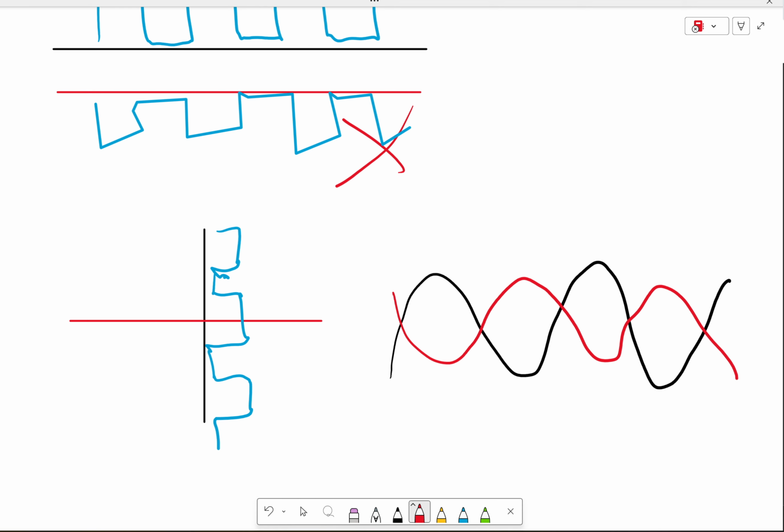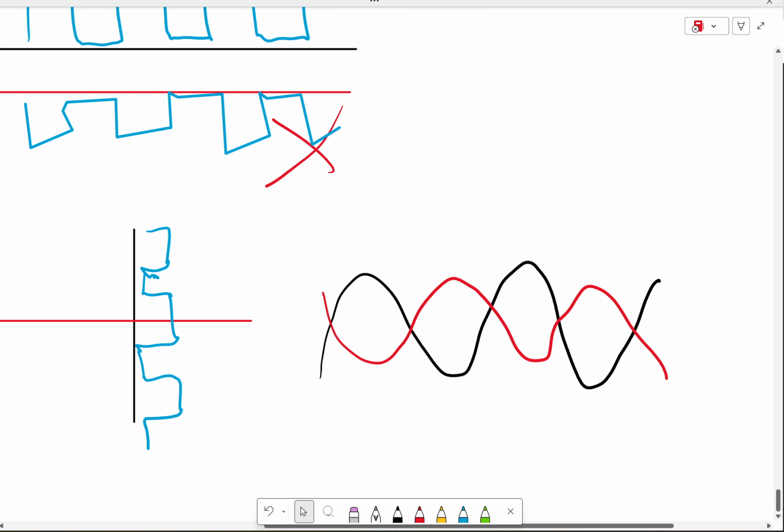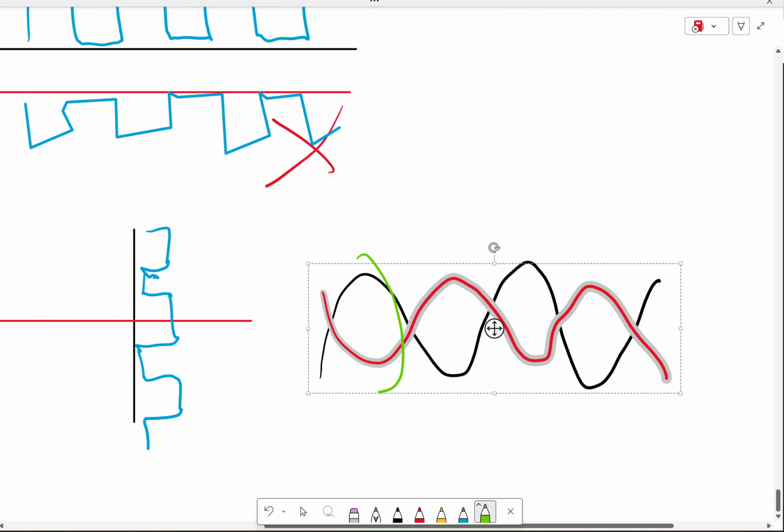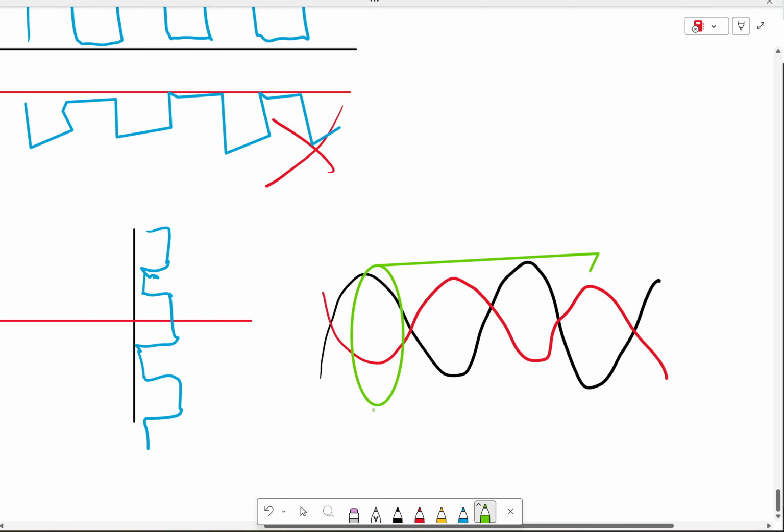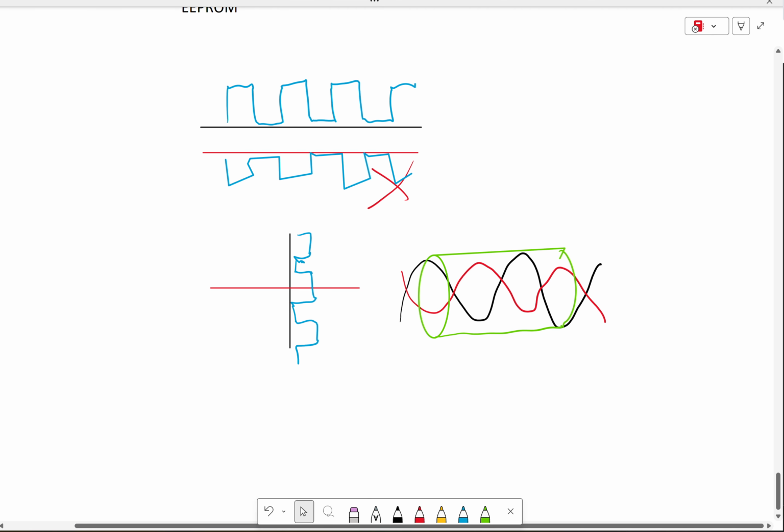We can take it a step further as well. I'm sure that you guys have heard of shielding, right? So if you shield a conductor, what exactly are you doing? You're enclosing that conductor with another conductor. That's exactly what you're doing. Shielding is basically just wrapping foil or copper mesh around some wires that you're trying to protect from interference. I'm going to move this a little bit. Hang tight.